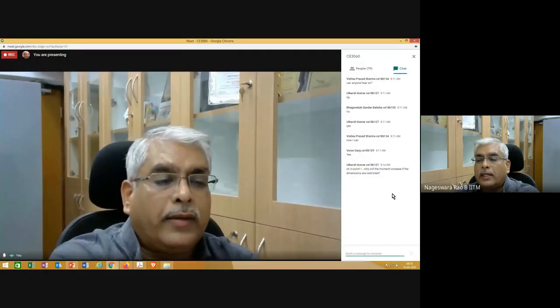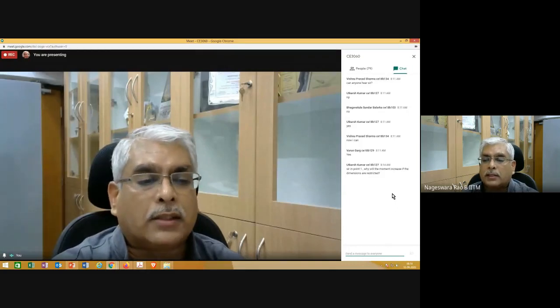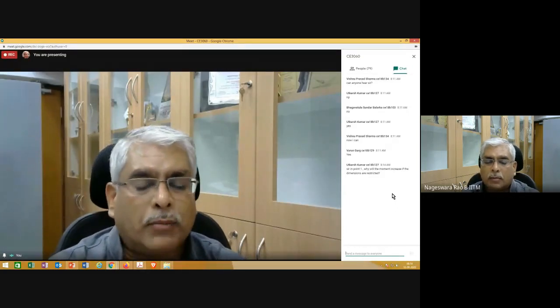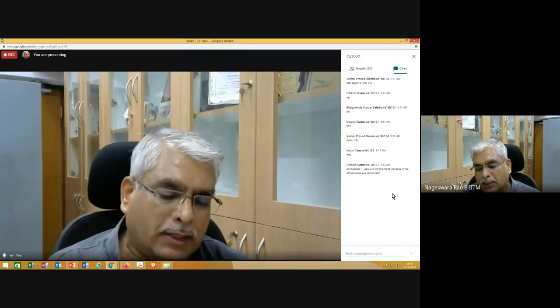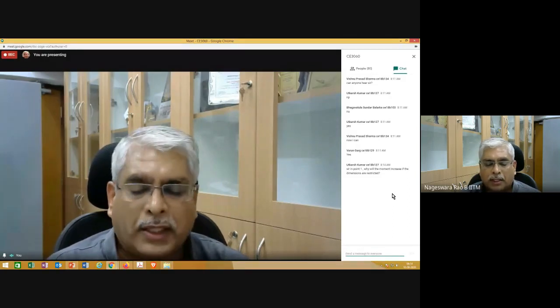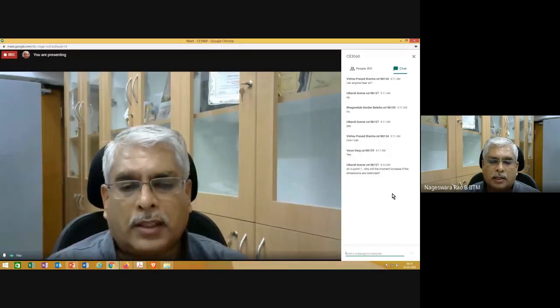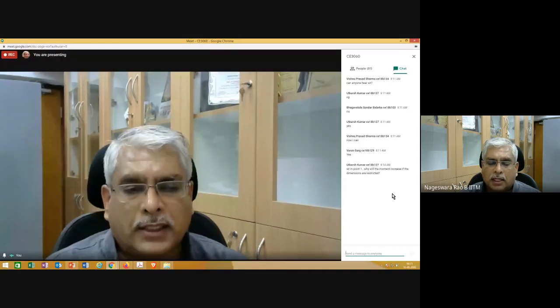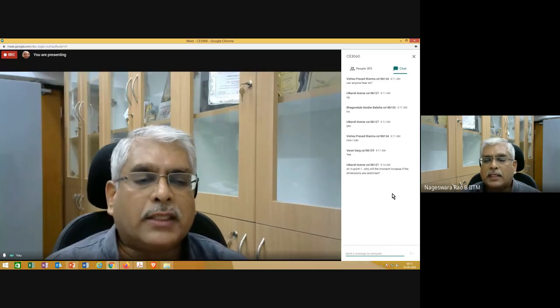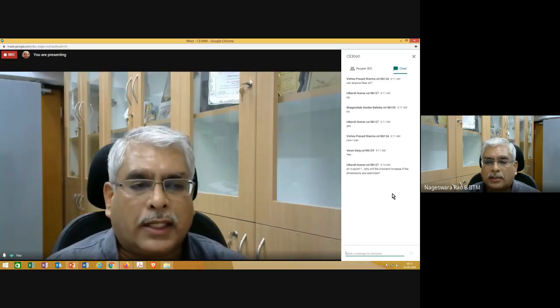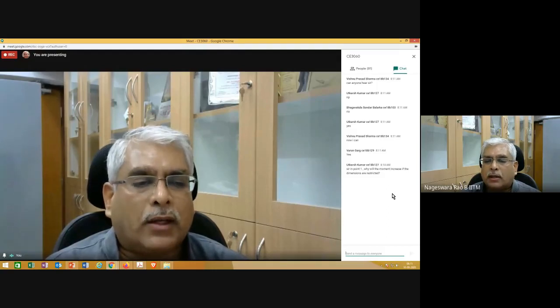Why will the moment increase if the dimensions are restricted? Please note that moment is not increasing. When you restrict the depth, your lever arm distance is going to reduce. How is the resisting moment generated? Resisting moment is generated by the tensile and compressive forces separated by this lever arm distance. Once the lever arm distance reduces, your moment carrying capacity also reduces.